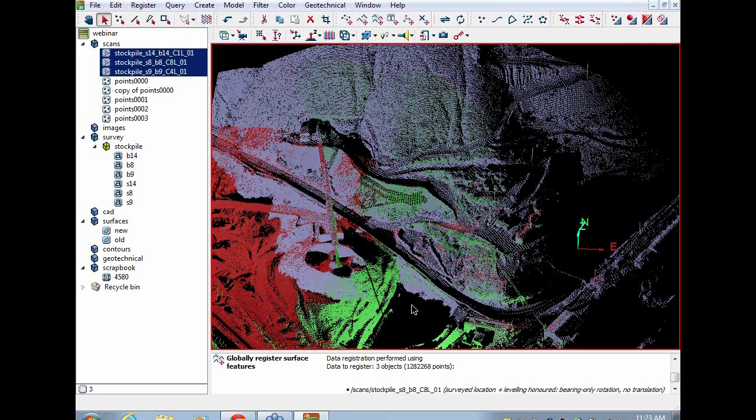That's a great question. In this instance, yes. This is by a stockpile that's being fed by a conveyor, which does cause a certain amount of dust to be in the air. But those spikes can be caused by several things. In the wintertime, the laser can reflect off of snow particles that are in the air, and it can be caused by that as well, or just debris. I've actually seen a flock of birds fly through a scan, and you get a few points out of that. But dust can be caused by anything floating in the air. As the scanner is sending out so many data points, it picks up even the minutest details like dust and snow.